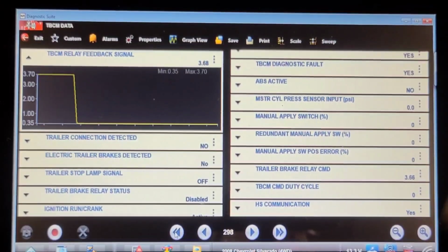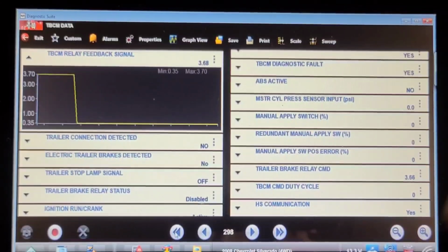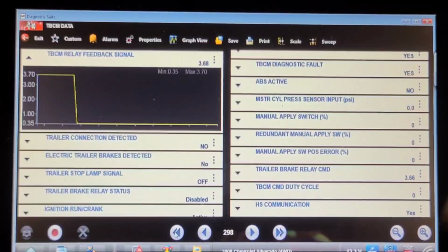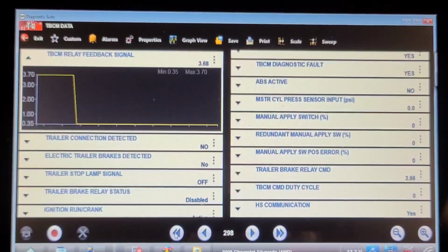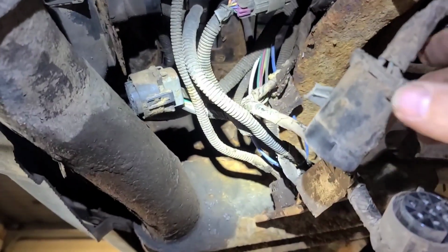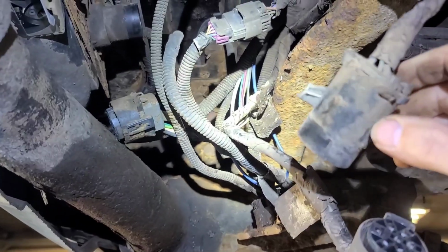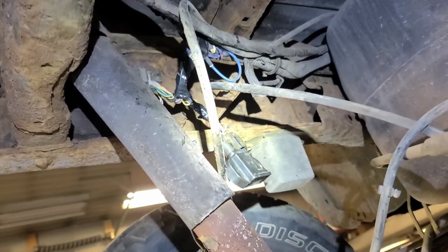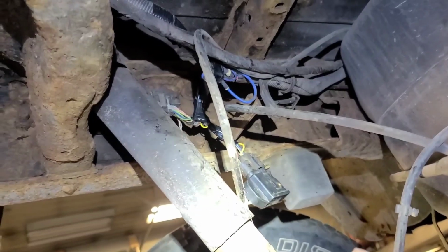So here's what happened when I plugged in the new relay. It went from 3.7 volts down to 0.35 volts. Exactly the same as the other one, or very, very close. Oh, brother. So I come to realize that this thing has a fifth wheel trailer plug-in as well. That's in series in the circuit or in parallel in the circuit. So I unplugged this connector. I put the original brake relay back in and it didn't change, but if I unplug that it goes to the bias voltage.